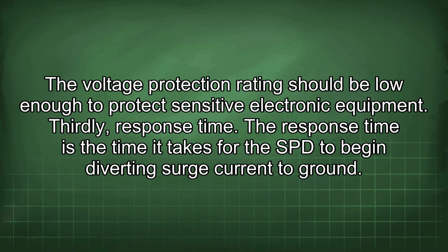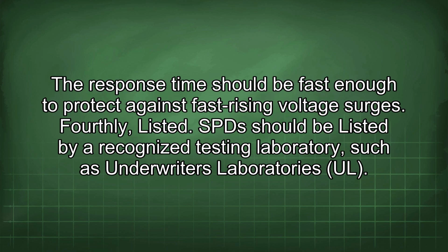Thirdly, response time. The response time is the time it takes for the SPD to begin diverting surge current to ground. The response time should be fast enough to protect against fast rising voltage surges. Fourthly, listed. SPD should be listed by a recognized testing laboratory, such as Underwriters Laboratories, UL.